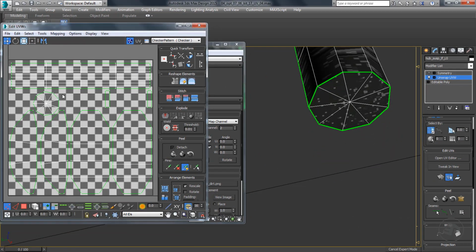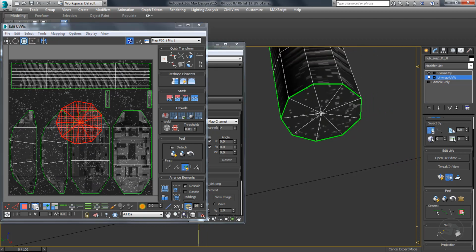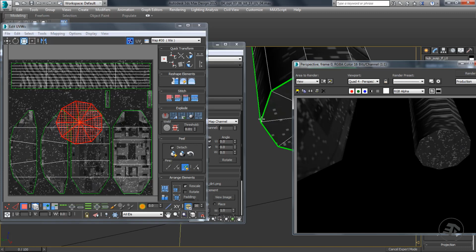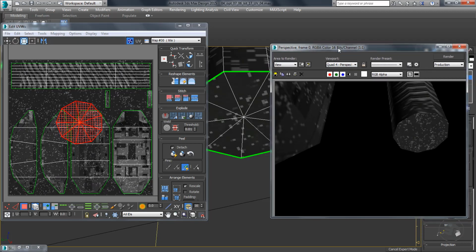We are now in the channel UV2. Any manipulation of the UV map you will execute cannot be monitored in the viewport. However, you can perform a quick render to monitor the wrapping process. When switching to the mix node, you still get the mix node result in the UVW editor, despite we are working on channel 2, and only maps with channel 2 should be visible in the editor. This can be considered as misleading information, and also another limitation of function inside the UVW editor.